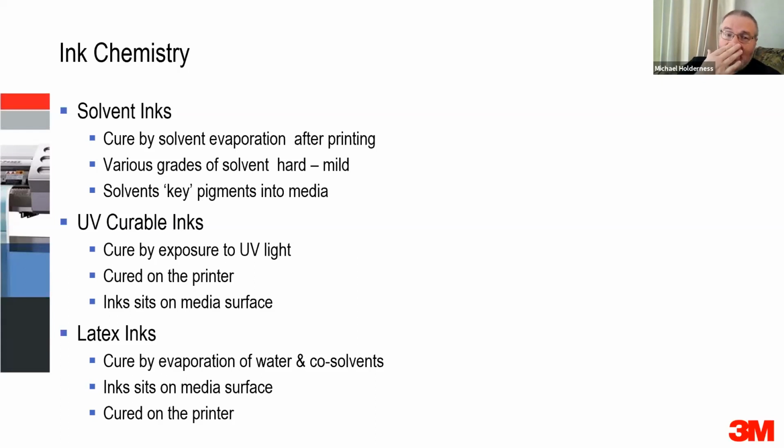The reason we use leading lamp cure is that it allows the UV ink a little bit of time to settle down onto the surface. So it tends to flatten the ink down a bit. So you get a slightly smoother surface if you leading lamp cure. Trailing lamp cure turns on the lamps directly after the print head. So as soon as the ink is laid down, it's cured by the lamp coming in behind. So different curing regimes will give you different looks. A leading lamp cure will give you a smoother look. A trailing lamp cure will give you a slightly rougher print.